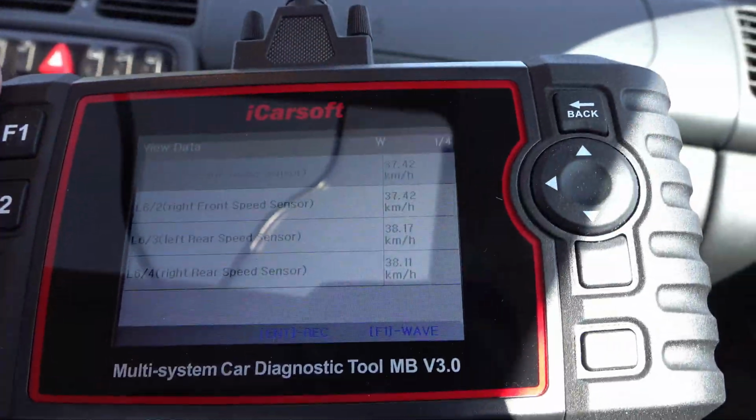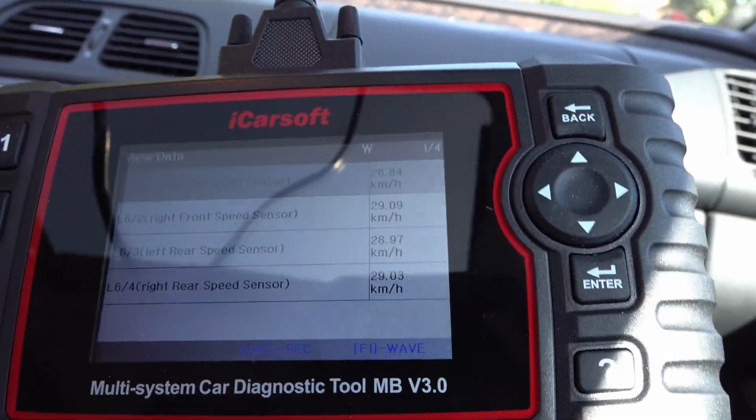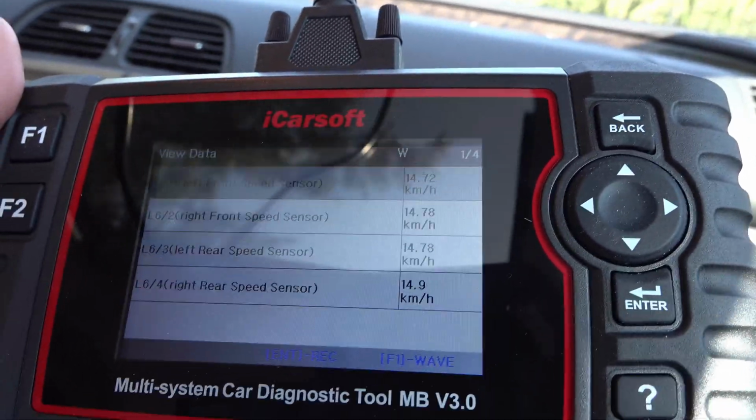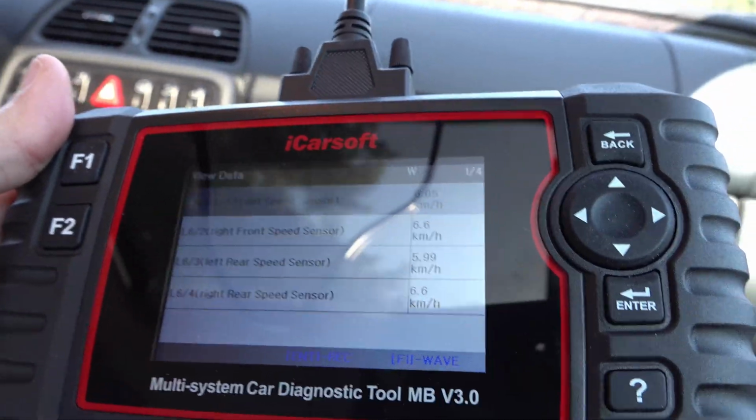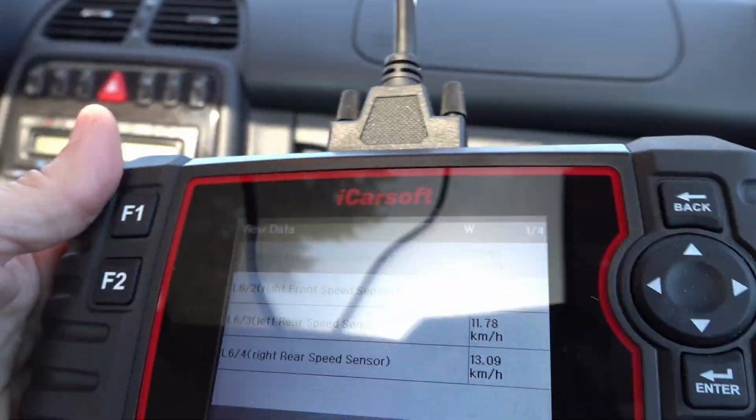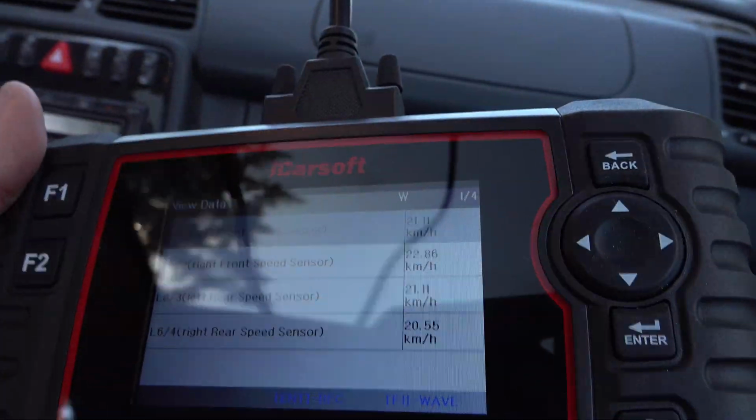So if this data is good, but it's not getting to the transmission control module, then there's something either wrong with the transmission control module or the cabling to it, because we're getting it from the brakes. Okay. So Di, we're getting closer. Yeah, so we know how to reset the check engine light. We know how to read our codes. Right. We know about the sensors. Yeah, we know the sensors are going to the brakes, but for some reason they're not going to the transmission control module.